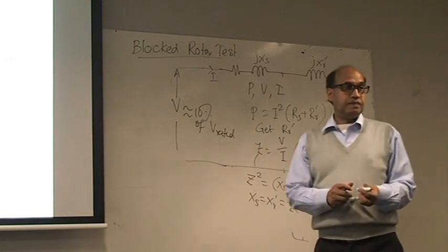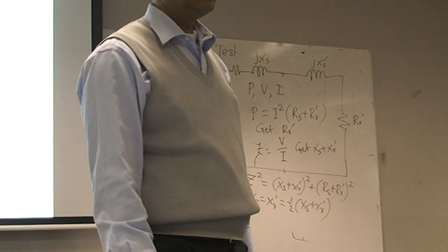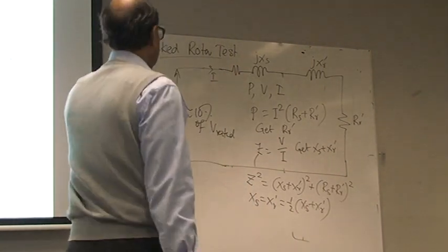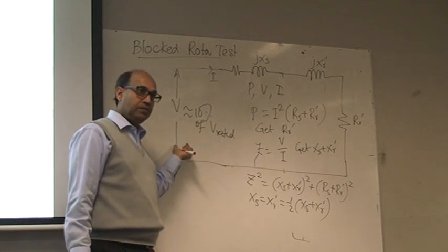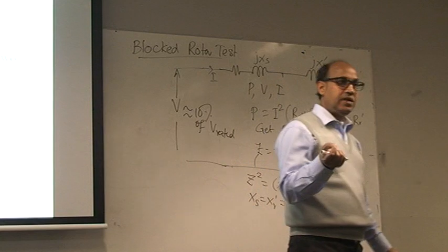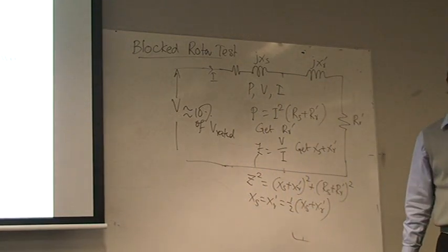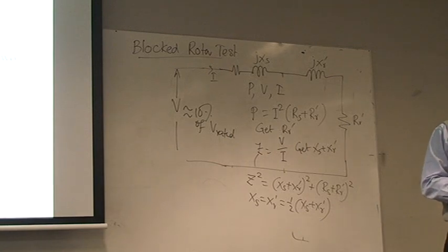Did the core losses, like core copper loss and impedance, not affect this? Yeah, because the voltage is very low. So because of that flux is very low. That's why core loss there will be there, but it will be very small. Because you cannot say that I get 100% accurate. You cannot, because you are ignoring something.